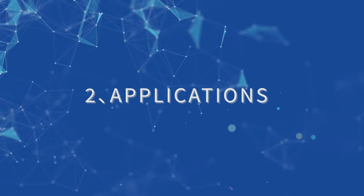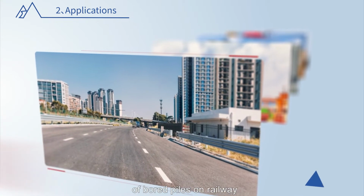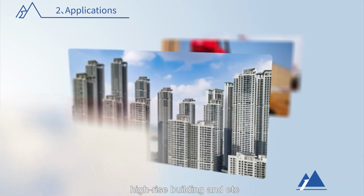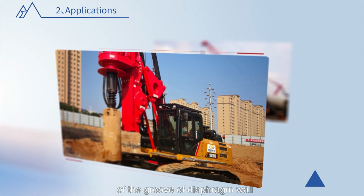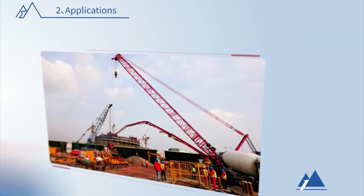2. Applications. The ultrasonic drilling monitor can be applied to hole quality testing of bored piles on railway, highway, port, high-rise building, and etc. Trenching quality testing of the groove of diaphragm wall. It can also be used to detect the thickness of sediment.